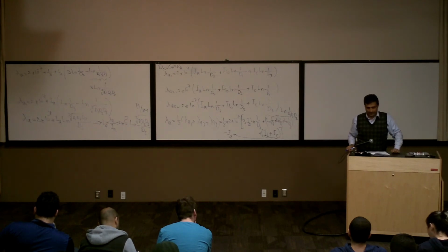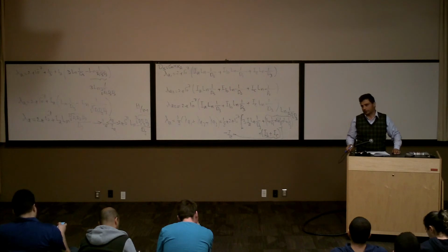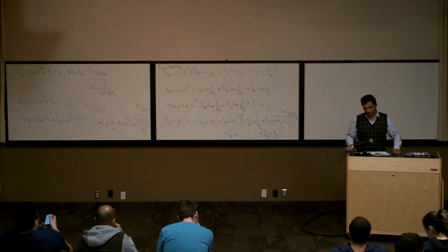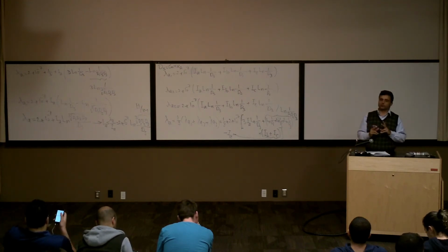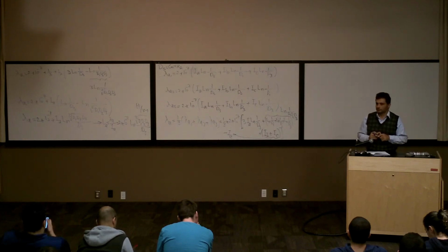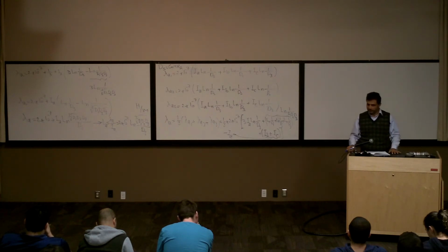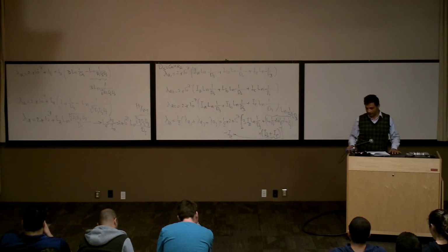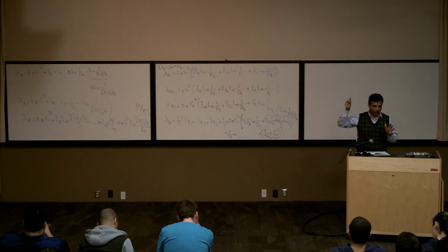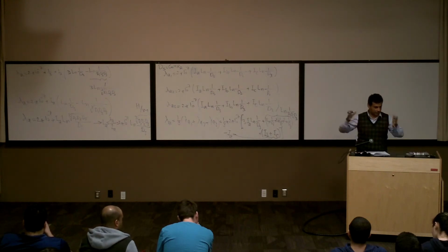The last thing is for very high current, when you have a lot of current, hundreds, thousands of amps, something like that. So what is the problem when the current goes up? What do we have to do? If you have 10 amps, say gauge 14 or gauge 25, right? If you have, I don't know, 15 amps, say I have to have a gauge 10, for example, right? What you are doing, you are making it bigger and bigger, right? When the current goes up, you are making the conductor cross section bigger and bigger, right?